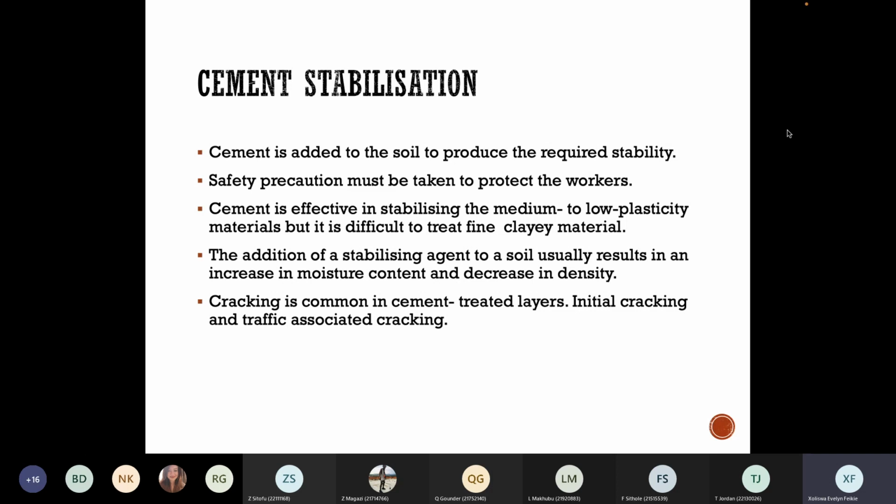That is a curing process, because if I take the cubes, put them in a bath, we'll put them in water. On site, you can't put them in water. You need to find ways to make sure that you don't lose the moisture because of the heating, right? Because of that heating, you will tend to lose moisture. You don't want to do that. You want to retain all the moisture, and then you use those methods.